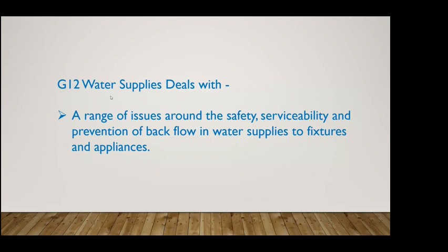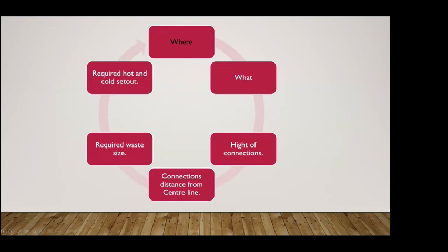But there is a 2022 edition, which is on Standards New Zealand's website, but because it's not quoted in the gas safety and measurement regulations as being the means of compliance, it's currently actually not legal. Although it's got a higher threshold for some things, like PEX pipe you can no longer use outside, compared to the previous version. And most things just carry over and are the same because they were there for a reason in the first place.